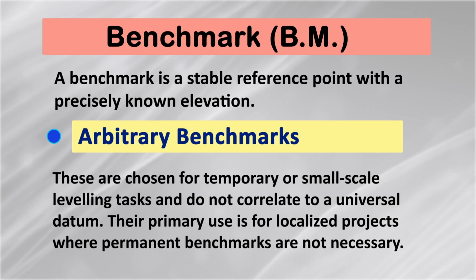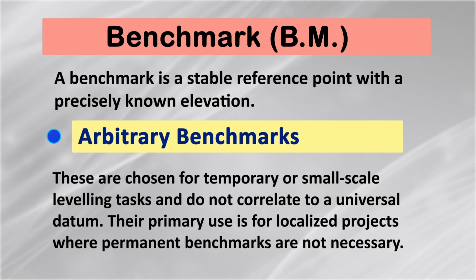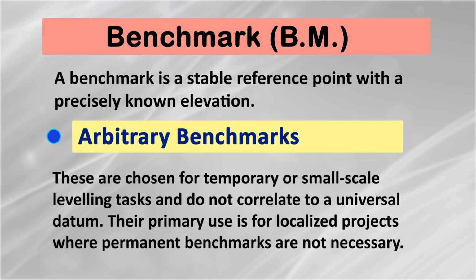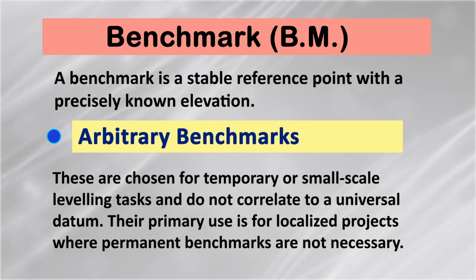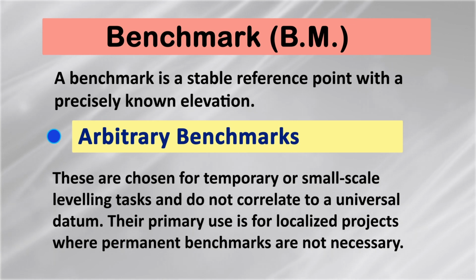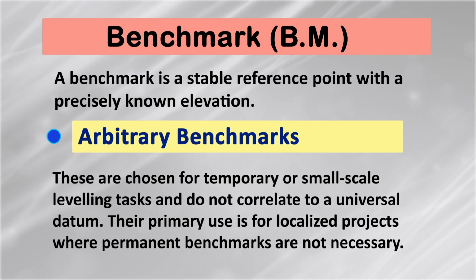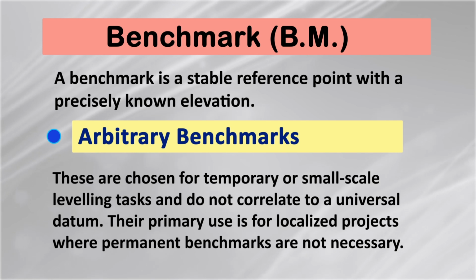Next is arbitrary benchmarks. These are chosen for temporary or small scale leveling tasks and do not correlate to a universal datum. Their primary use is in localized projects where permanent benchmarks are not necessary.